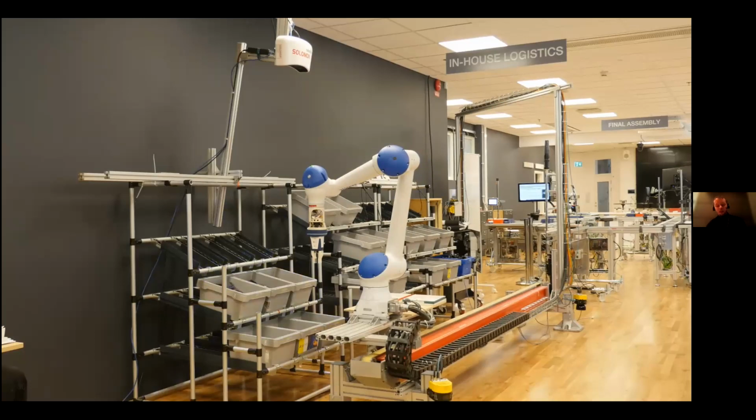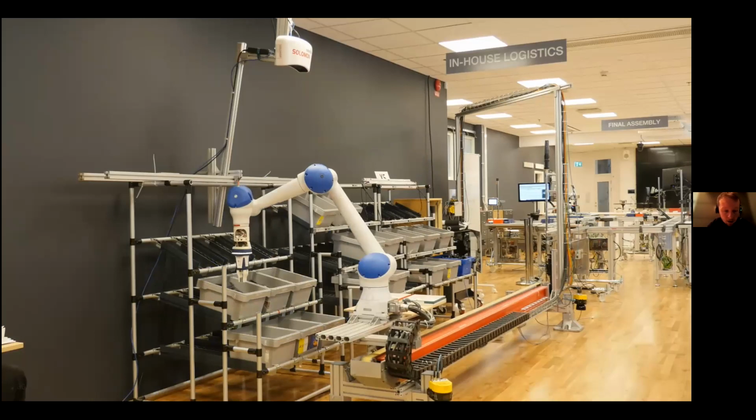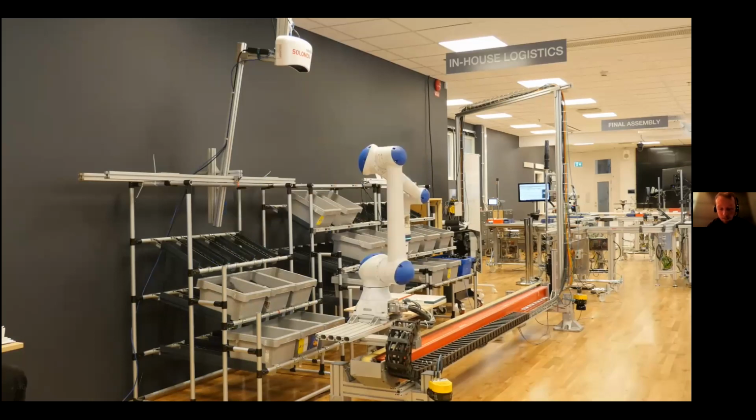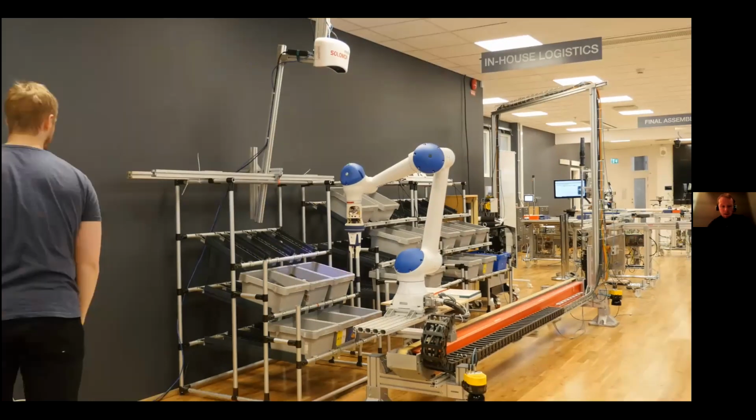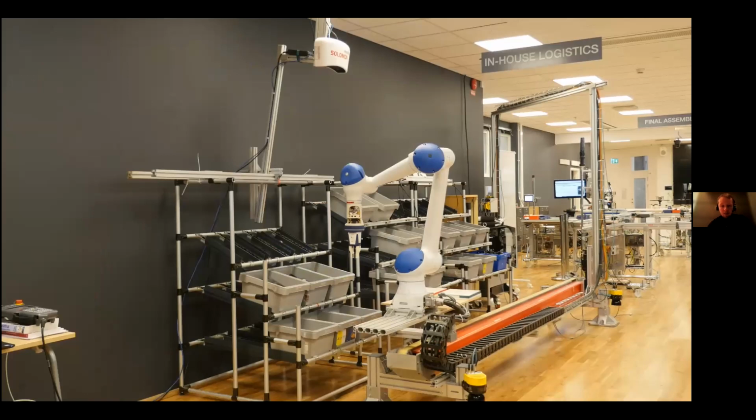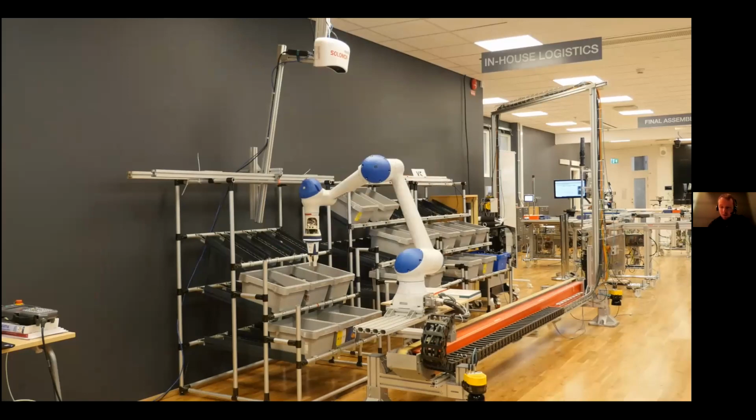You can see on the LED indicator on the robot whether the pick is successful or not. So it's yellow when the robot moves. And then once it has gripped the component successfully, the LED turns green. And we have a lot of optimization to do with the robot's movement as well, and to make scans in parallel when the robot works. But this is a first draft of this process, and we will optimize it further along.